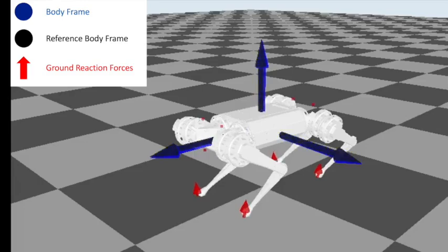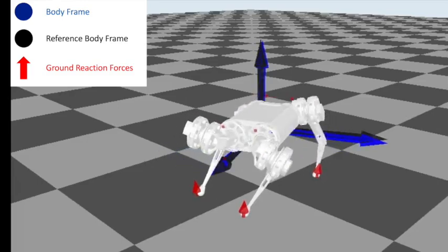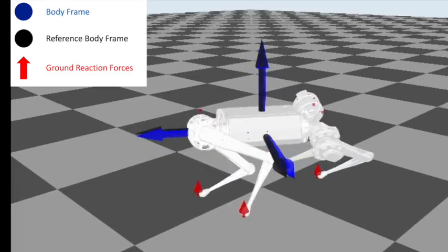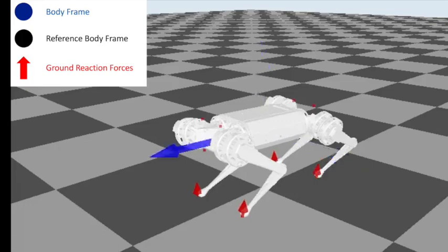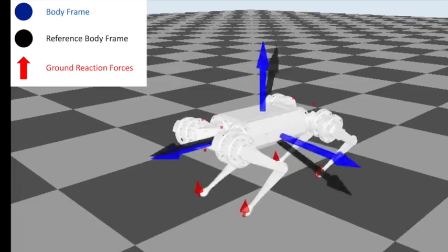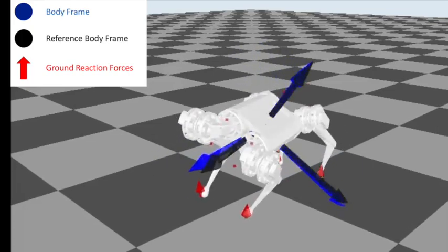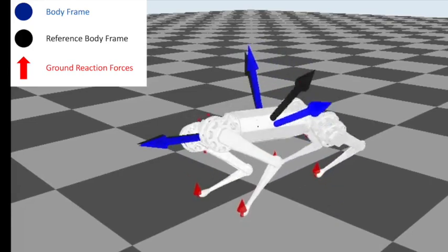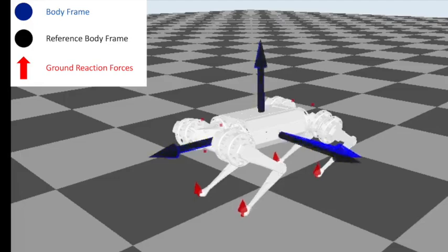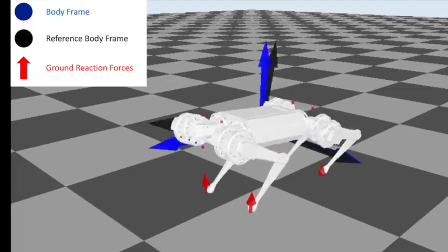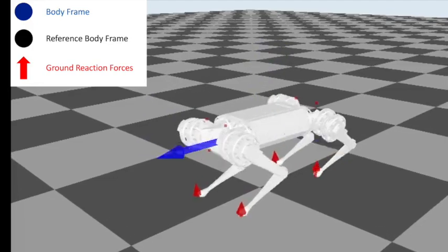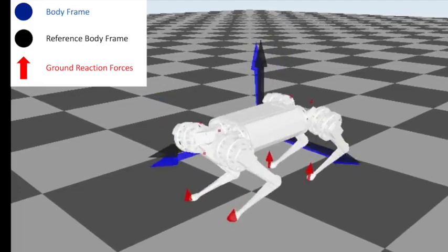Variational-based linearization, which involves linearization about a reference trajectory, exploits specific variation expressions on the nonlinear manifold SO3, which allows for parameterization of the error directly based on infinitesimal rotations. The ability to parameterize the error in this way offers a significant advantage over typical dynamic models that employ Euler angles, which can suffer from singularities, or quaternions, which are significantly more complex to deal with and suffer from issues like the unwinding phenomenon.